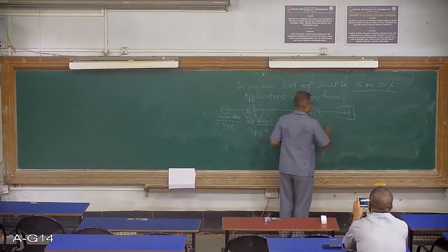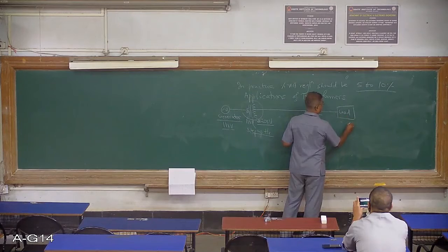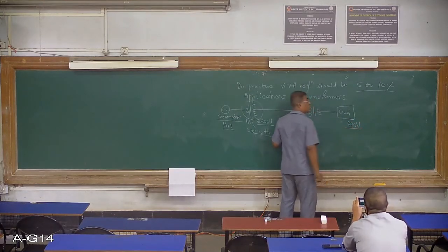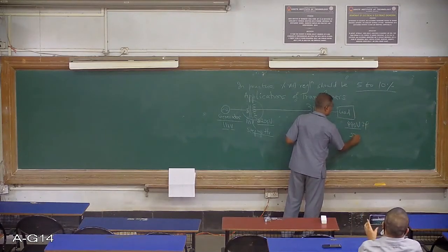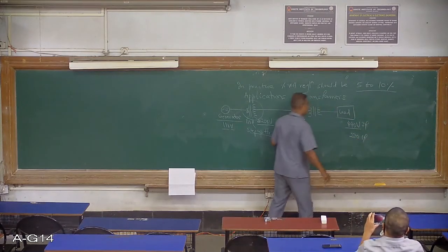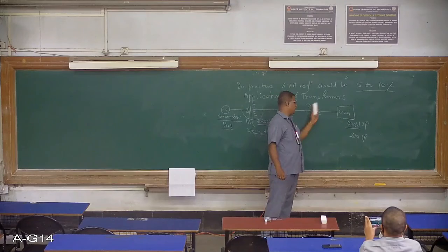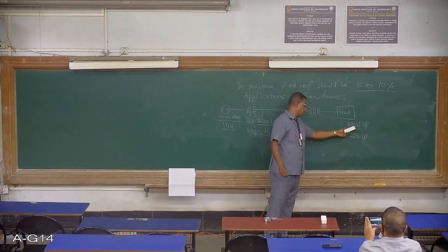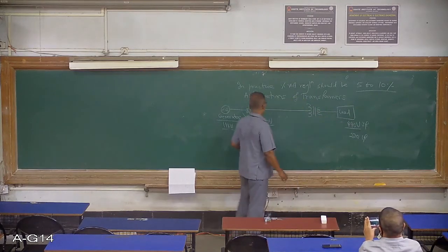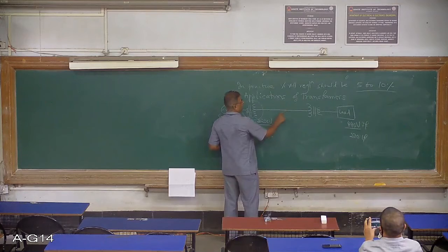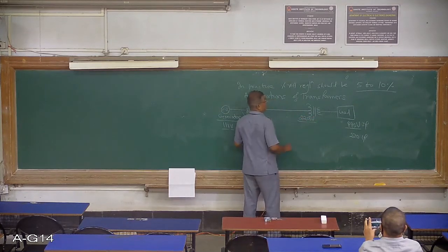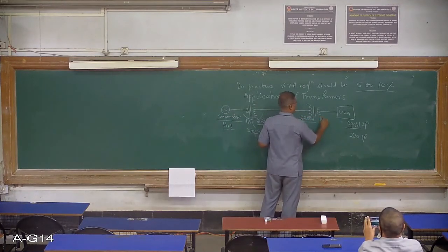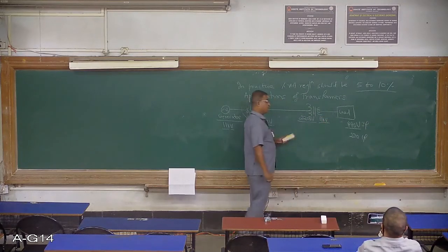At the load, the level of the voltage has to be reduced to 440 volts 3 phase or 230 volt single phase. So in the rear end of the power system, at the domestic level, the voltage has to be reduced. So the 220 kilovolt voltage has to be reduced. First it is reduced to 11 kilovolt in the first stage.